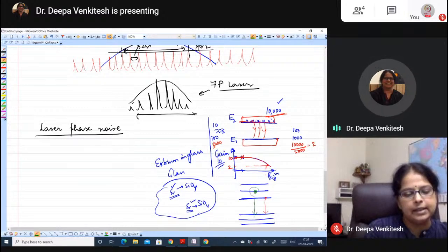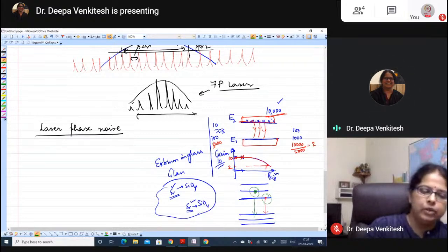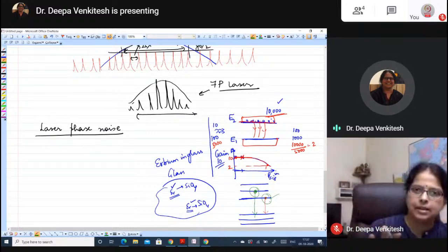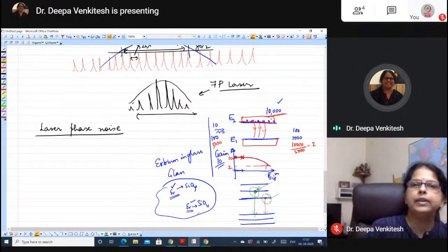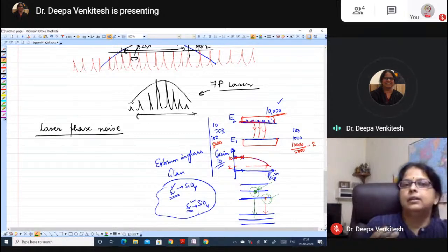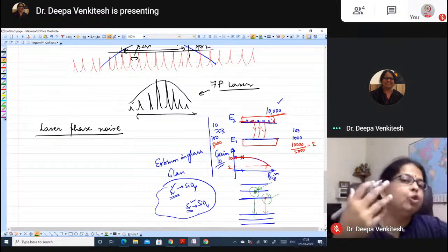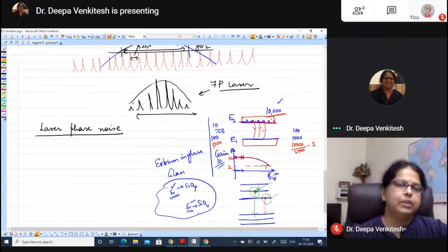It's like saying that this set of ions and that set of ions may not talk to each other. You can saturate this set of ions, which correspond to erbium in a specific electric field matrix in glass, but that doesn't mean that the set of ions sitting in a slightly different energy state, in a slightly different glass matrix environment, get saturated.